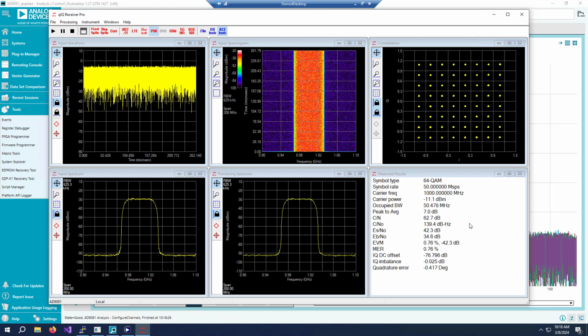system. So what I see here when I look at this is carrier to noise is this expectation of what I'm expecting to see signal to noise ratio wise when I get my final data here. And this number here is a lot bigger than this number here. This number is on the order of 62 dB, but my EVM is only like minus 40 dB. So I'm a little bit disappointed in the quality of the final demod here. It's not quite as good as what I would like it to be.